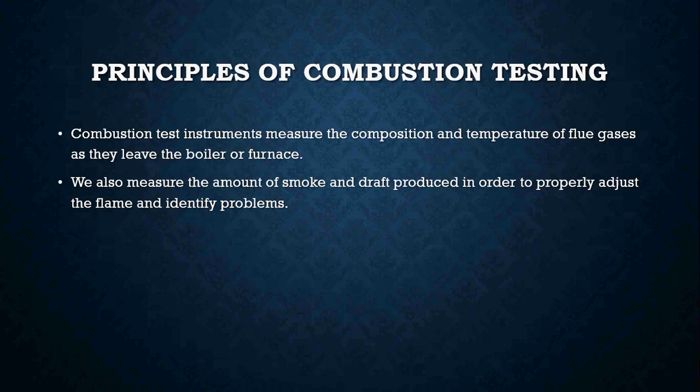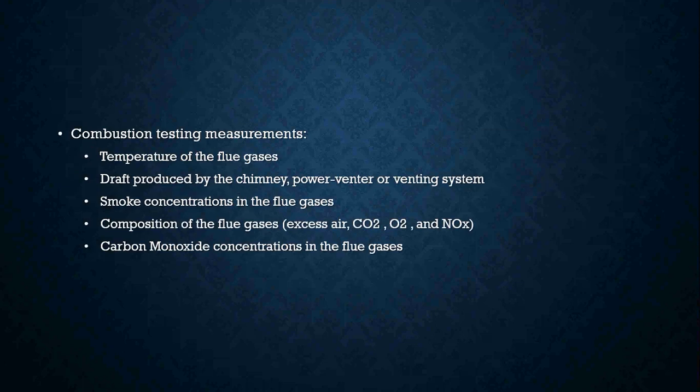That is really important when we are thinking about combustion efficiency. We are measuring things. We are measuring temperatures of the flue gases. We are measuring the amount of smoke that's going out the flue pipe. We are measuring the draft in our flues to see whether or not we have problems.